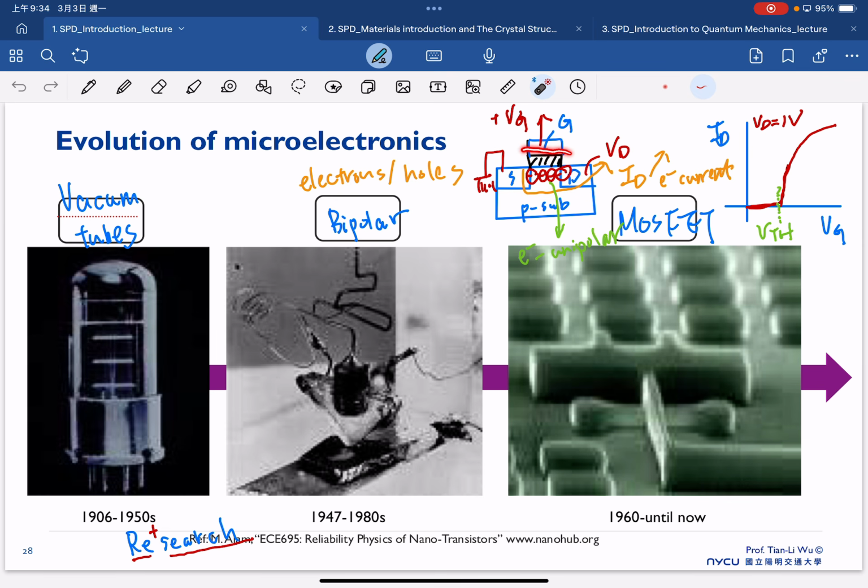And because we have the dielectric here, you can imagine the dielectric is a kind of barrier that will stop our electron flow toward the top. That's why all the electrons will stay in this region. And at the meantime, we apply the drain bias on the drain side. Since the electrons cannot flow to the top, but we have the positive drain bias, the electrons will start to flow from source to drain. In the end, it becomes the drain current here.